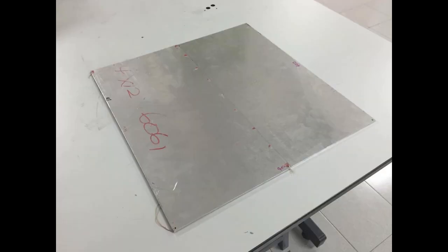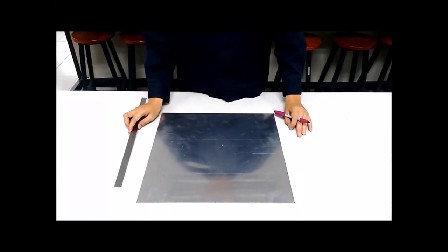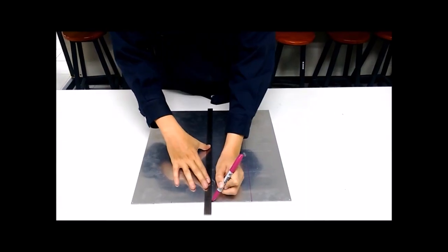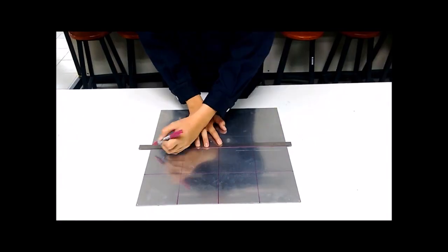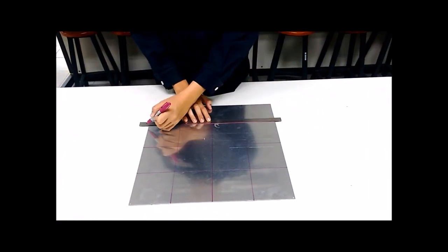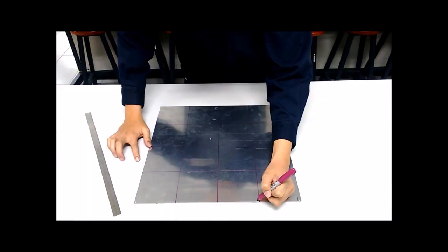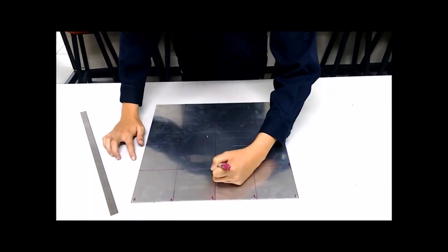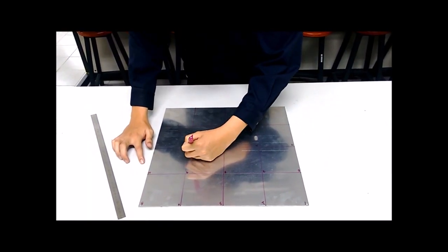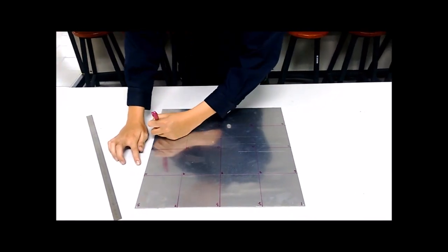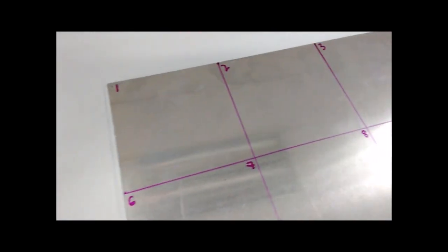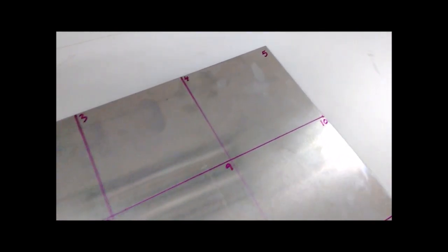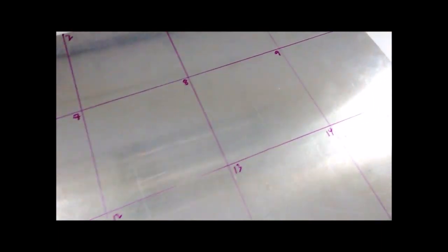The structure under investigation is made from 4 mm thick aluminium sheet. Before the structure undergoes the measurement process, the structure setup is performed first. The structure is discretized into several elements and nodes. The purpose of discretization is to view the mode shapes of the structure in the simulation result. A larger number of elements and nodes does not mean a better result will be obtained, vice versa. The determination of the number of elements and nodes highly depends on the initial guide provided by the finite element result. Each node is marked with a number to ease the measurement process.